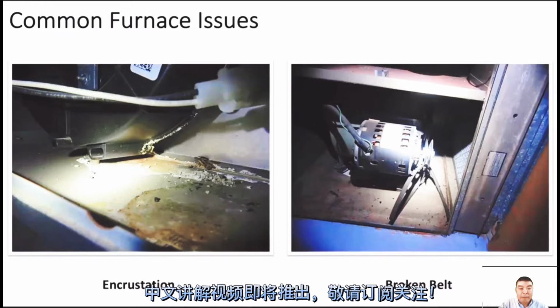That causes trouble if the condensate water cannot drain out. The condensate water will dissolve some acid and cause an acid smell. If you go to the house, you will smell that acid smell. Normally that comes from a high efficiency furnace whose condensate drain is clogged.